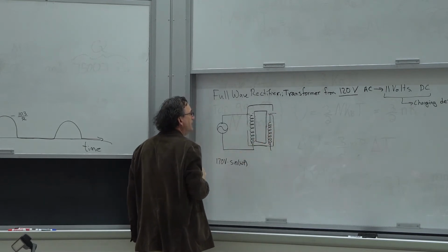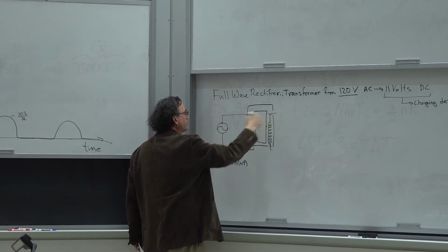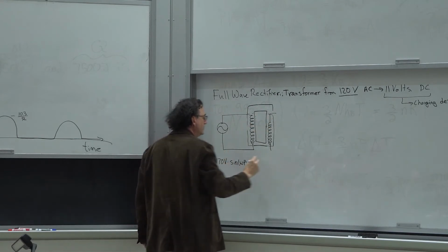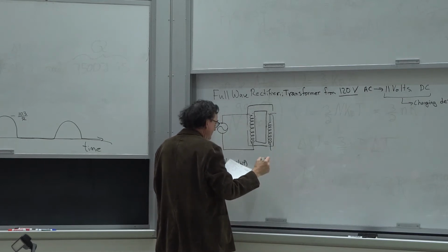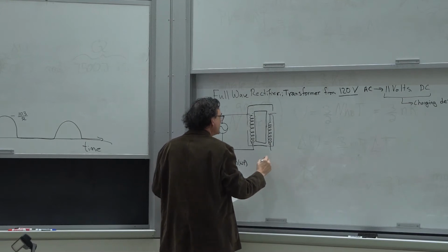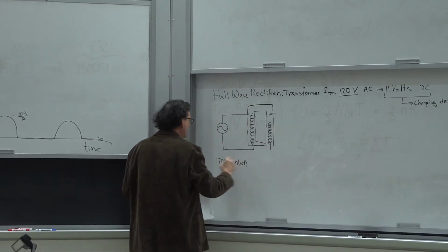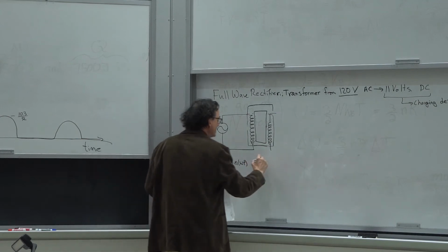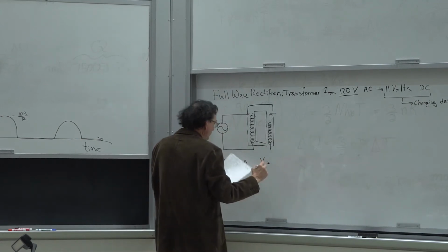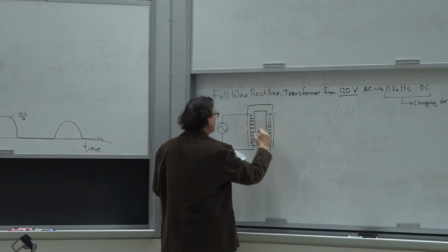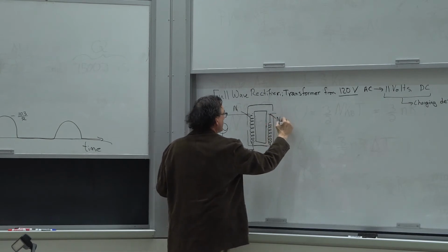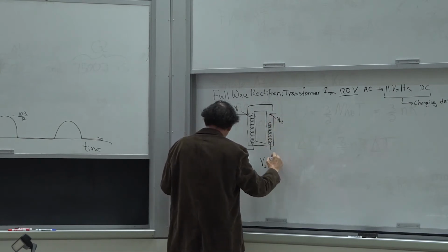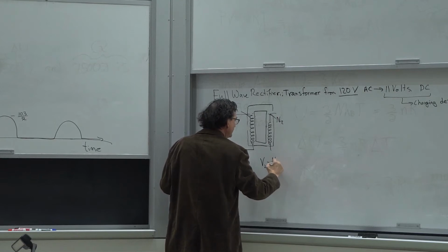That looks more like an inductor, and so the magnetic flux can go through here. Now we use a relation from our earlier electricity and magnetism course, which says that if this is the primary voltage V1, then the secondary voltage V2 is equal to, there are N1 windings on this loop and N2 windings on this loop, so V2 is N2 divided by N1 times V1, right?